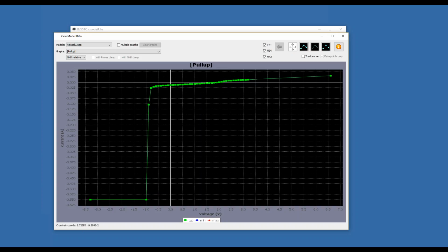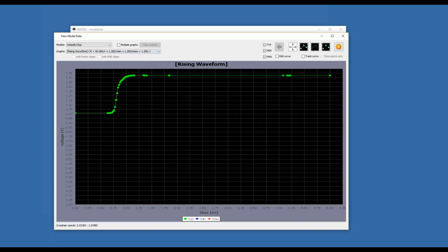What's happening is the load line should match here, and it's not. So when you simulate this, it's going to give you one or the other. If the real IC is supposed to be 1.01 volts, it might give you 0.98 in simulation, or vice versa.